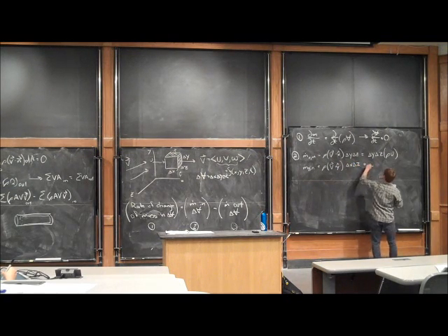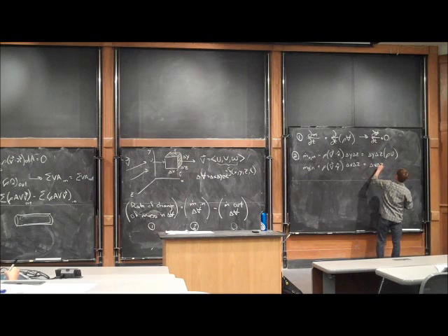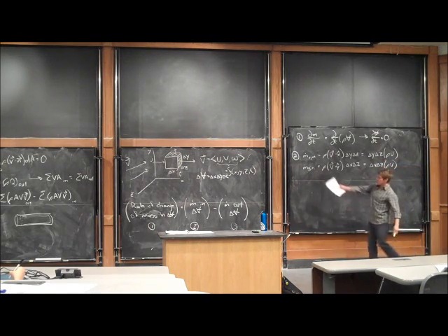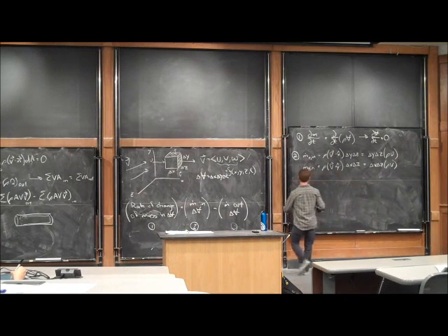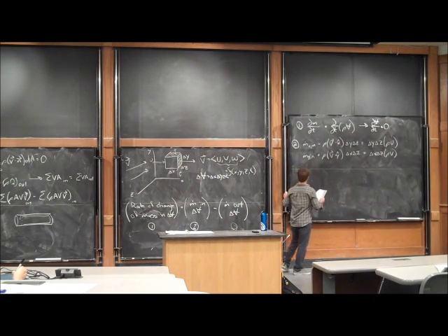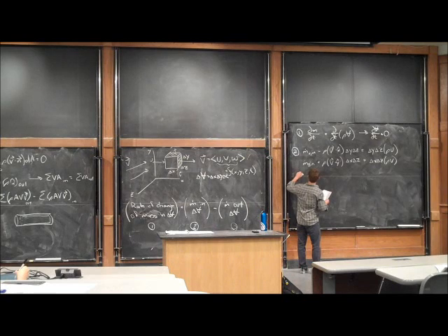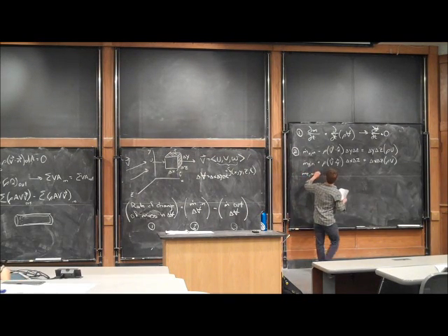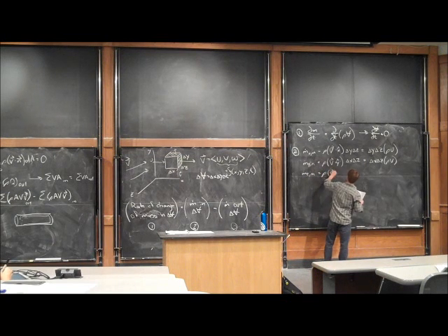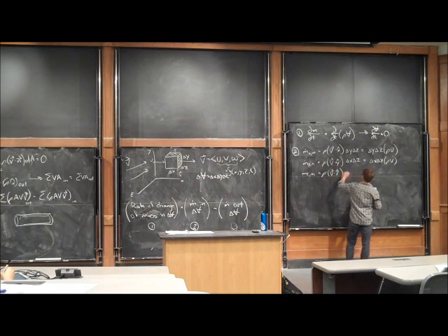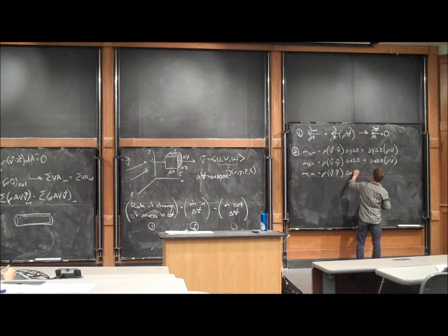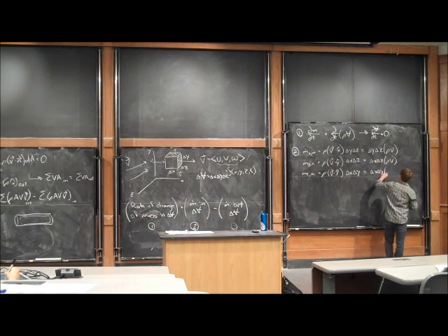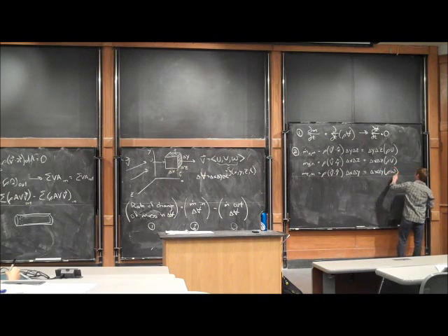That is equal to delta x, delta z times rho v, where v in this case is the y component of our velocity field. And our mass flow into the cube in the z direction is going to be rho times V dot z hat times delta x, delta y, which is delta x, delta y, rho w.